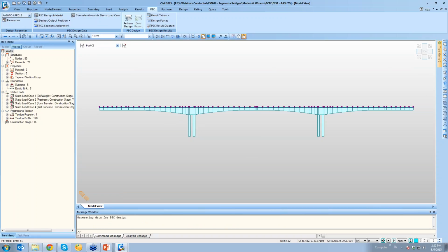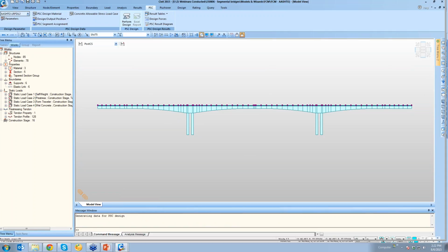Okay, so I have one more question. If we import a section of a girder from AutoCAD, can we still do the automatic design like strength check, etc. in the model, or do we need to assign the cross section in the model itself to do design in the software? Yes, you can do it from AutoCAD as well. What actually matters is the parameters that have been provided, right? You have provided the section size, so I and all would be calculated in the software and taken up, as well as the length for the design and all. In fact, there is a small input needed if you are using the SPC, but yes, you can perform design for that as well.